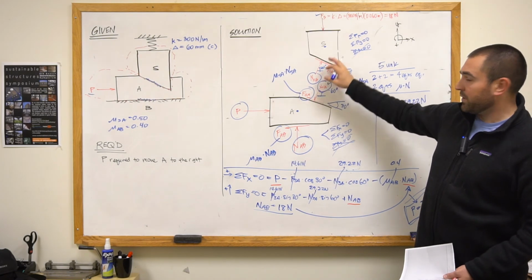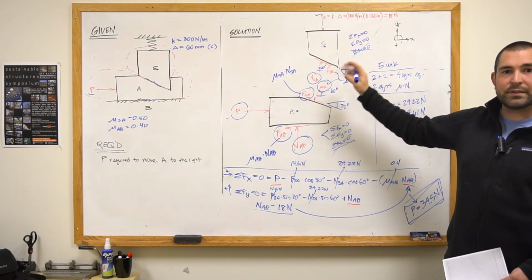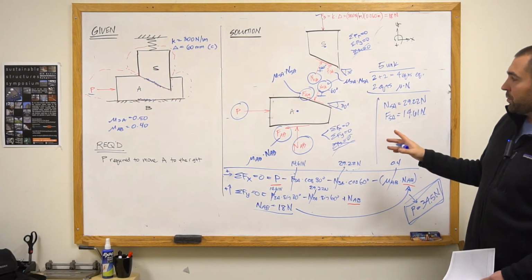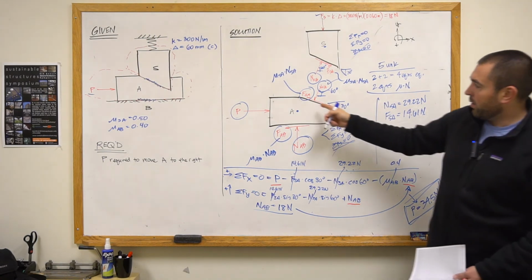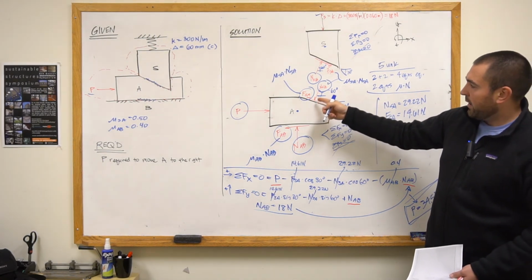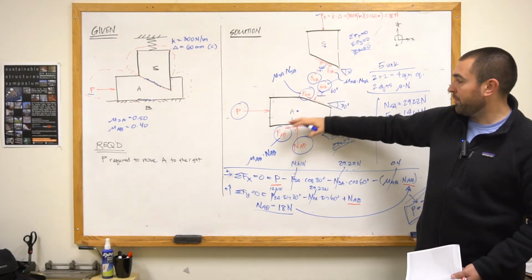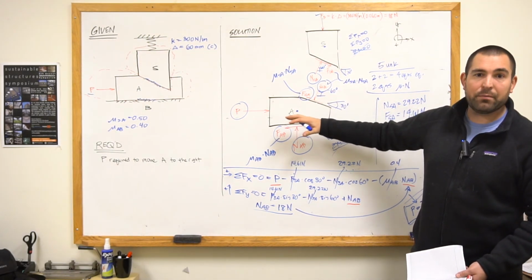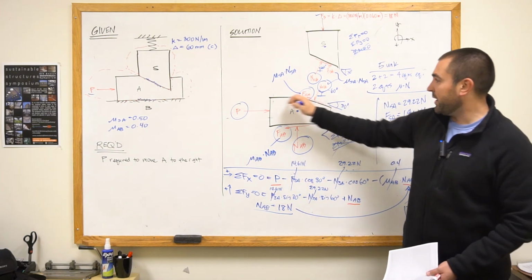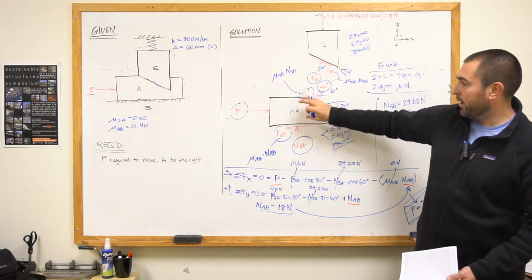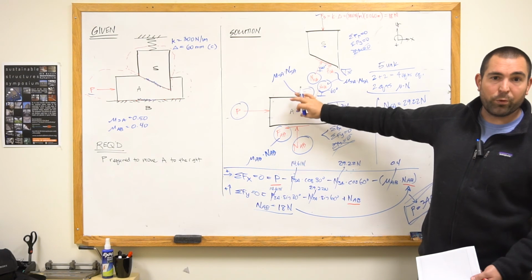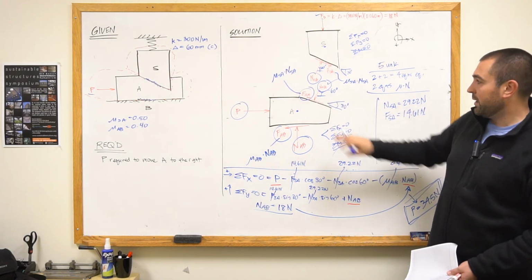Showing the friction forces and the normal forces across an interface as equal and opposite are crucial. Here, recognizing that the interface between S and A will only slip if the interface between A and B are slipping at the same time, because they have a similar rigid body that they're both connected to.